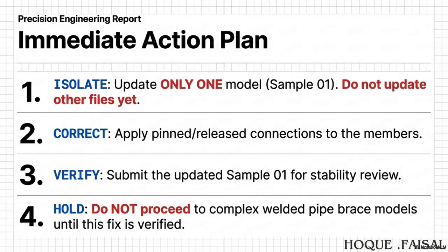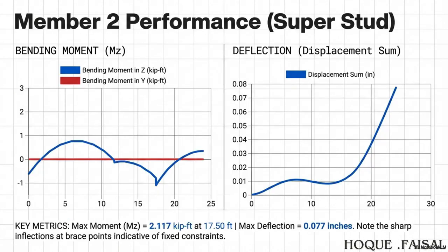Pinned. Now, second scenario. Imagine you take that same broomstick and you bury the bottom end 2 feet deep in a bucket of quick dry concrete. Okay. It's solid now. It's solid. And then I come along and push the middle of the stick. What happens now? It doesn't rotate. The whole stick bends.